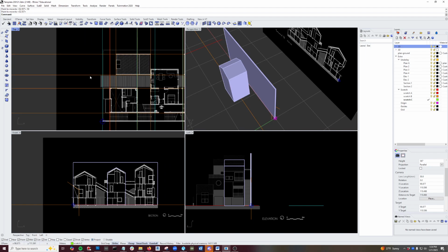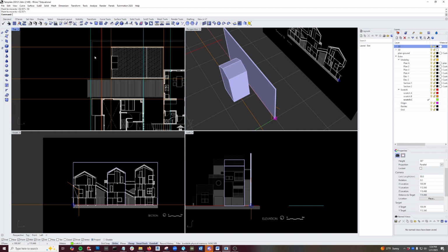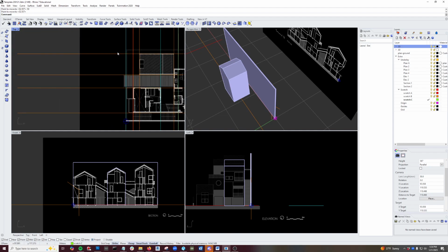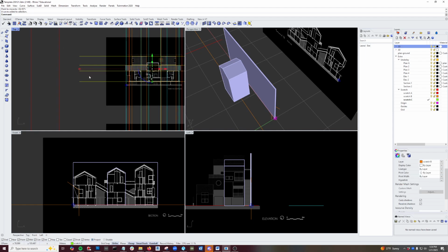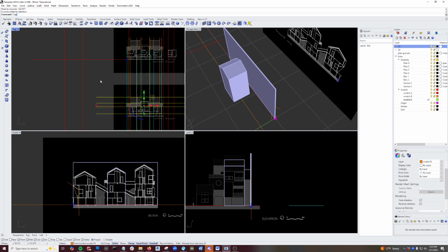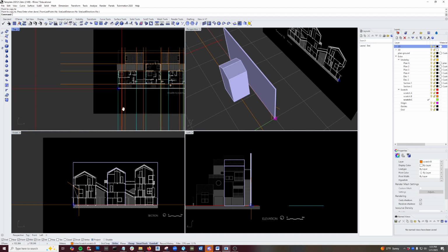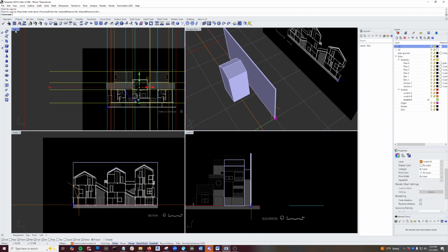And one of the things that I think is really good to do is you draw a line and move them in even increments instead of just tracing. So instead of being 2.23451 meters, it's 2.2 meters or whatever. And because these are all lined up and because they're all 50 meters apart, you can also copy these grid lines up 50 meters and see how they register on the next plan, right? You can see there that they're starting to line up, right?